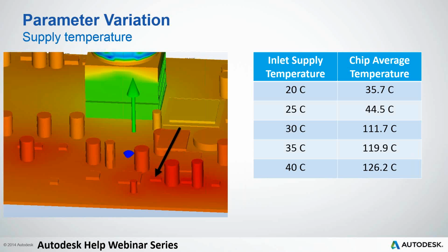I didn't pursue what happens between 25 and 30 C, but if I was really designing this, that would be my next question, because obviously our criteria was 75 C. So maybe also look at the flow pattern, like you mentioned, not just the temperatures, and see what's going on. Yep, and I would really chase the mesh, but if you're getting mesh independent results, then this is really occurring. So, yep, thanks, Marwan.